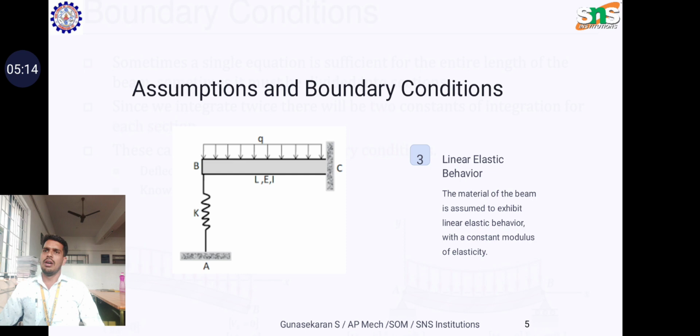Here in structural engineering, assuming a linear elastic behavior simplifies the analysis and design of elements like beams, allowing for accurate predictions of deflections and internal forces under typical loading conditions. This assumption is valid as long as the applied stresses do not exceed the material yield strength.